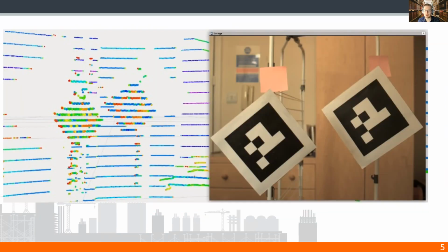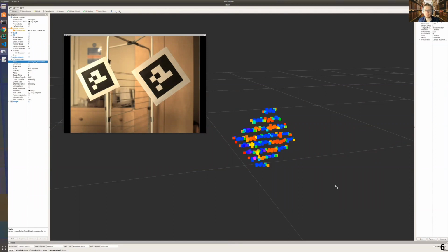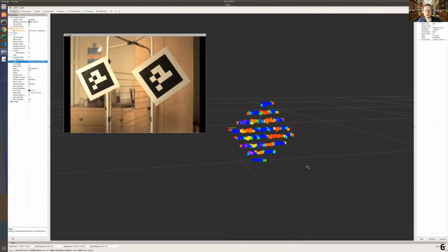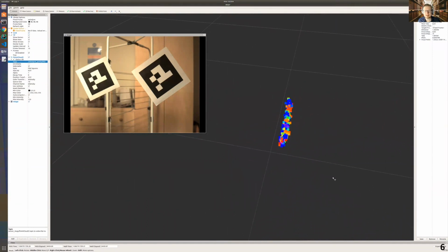Okay, we know how the static and mobile devices work. Now let's see how I measure accuracy in our paper. Imagine that I want to scan such a square target, which is very thin because it is simply a sheet of paper. I place my LiDAR on my desk, so the LiDAR is fully static, not moving, not using the SLAM technology, and I scan the whole scene. The result is such a point cloud. When we filter out the background and leave only one target, that will be the result, a small portion of the whole point cloud, which represents just the target.